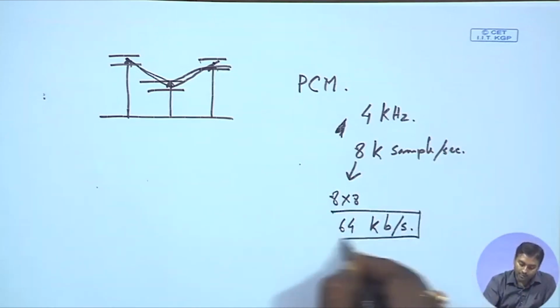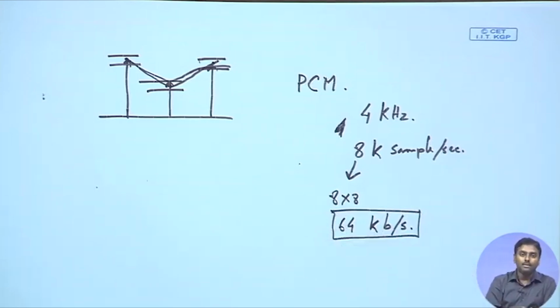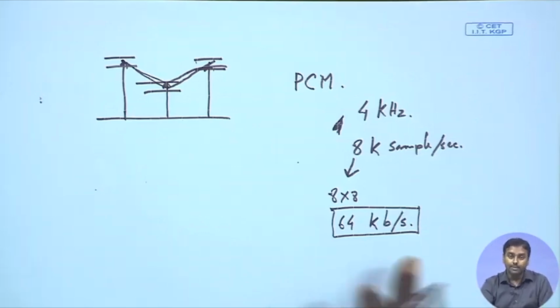So, that is why voice is always transmitted at 64 kbps. This is a de facto industrial standard, which has happened because of this PCM encoding, which has 256 representation levels for quantization. Okay. So, we have now seen that there is a quantization error happening due to this process. So, can we characterize this quantization? Let us try to see if we can do that.